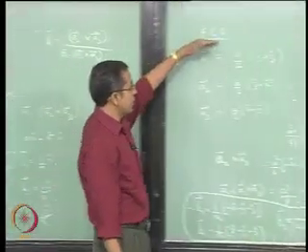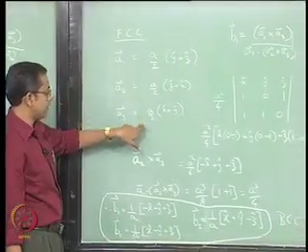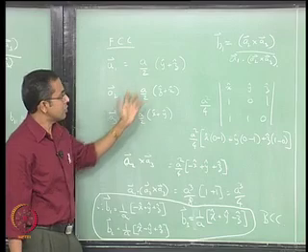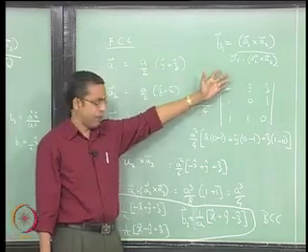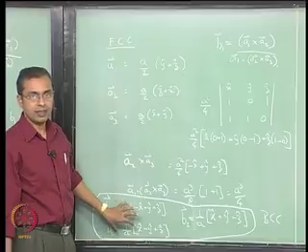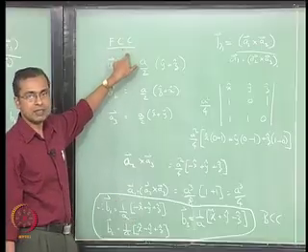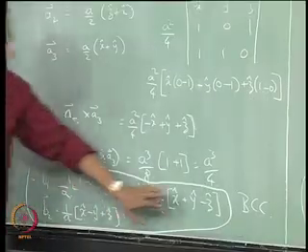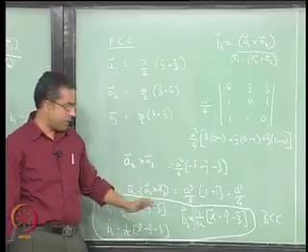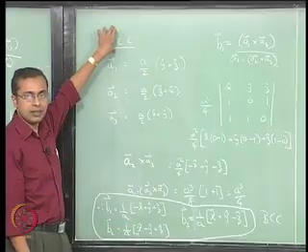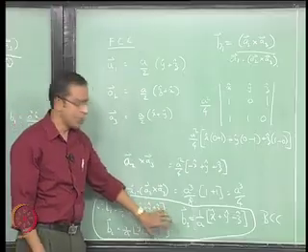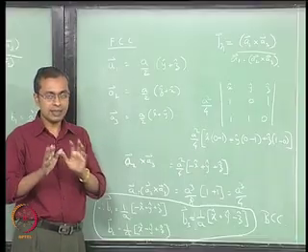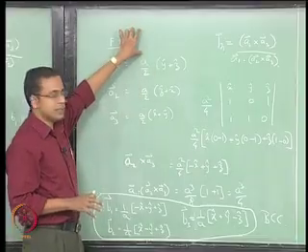If we start with a face centered cubic material and take the three characteristic vectors that represent it, and run through the calculations for reciprocal space, we find that the reciprocal lattice generated has vectors similar to those of a body centered cubic structure. So if you have a sample that is face centered cubic, you will have to plot the points in reciprocal space the way you would for a body centered cubic material. We are only talking of geometry. Geometry in real space is face centered cubic.